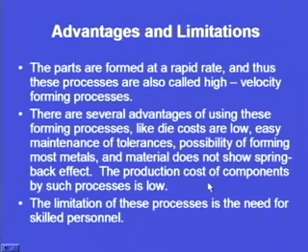So, just to have a brief review of what the advantages of these processes over normal forming processes are, we will see that there are several advantages of using these forming processes, like die costs are low, easy maintenance of tolerances, possibility of forming most metals, that is one versatility of this process, and material does not show spring back effect. So, there is no spring back effect in case of high energy rate forming processes. The production cost of components by such processes is low. So, the processes are economically justified.